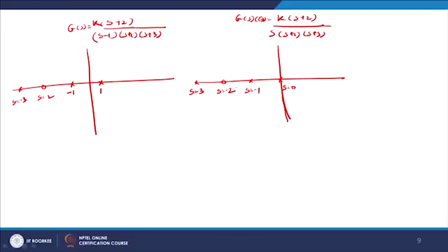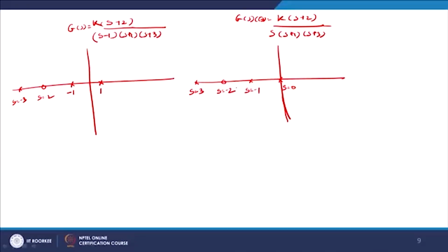Now our aim is basically the stability of the system. The system is to be stable. Therefore I have taken this plant G(s) into C(s). Now we want to draw the root locus. How do you draw the root locus? I think you might have studied it in the classical approach. The root locus starts from poles and terminates at zeros. So you will find that there are 3 poles and 1 zero.